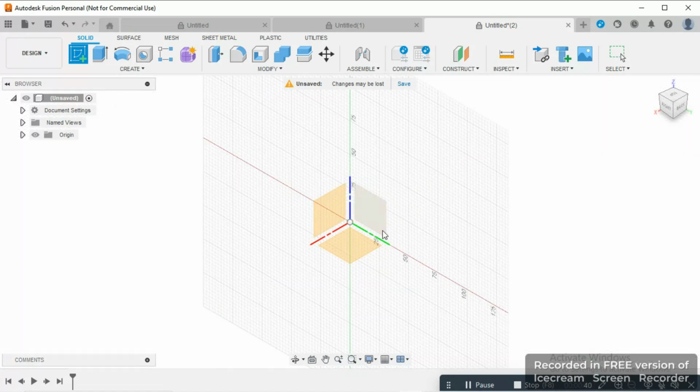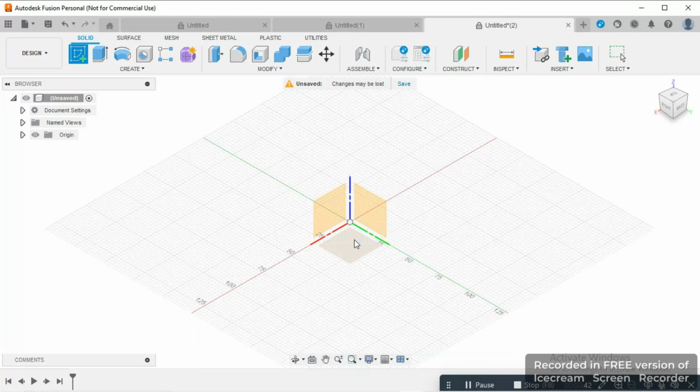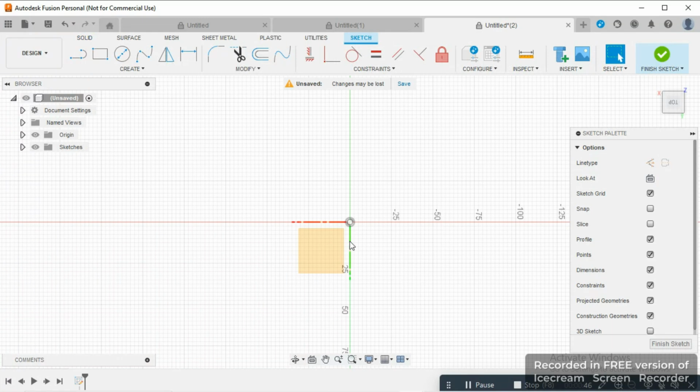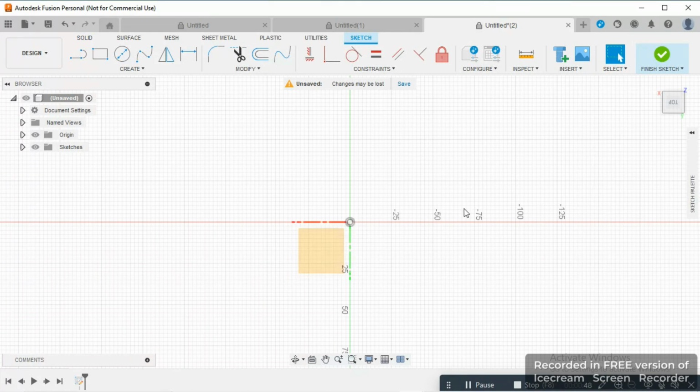Go ahead and click on Create Sketch. On the Create box, we can create on any plane. So I choose the bottom plane. You could observe that we are looking at the top view, straight at the work plane.